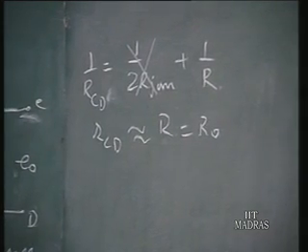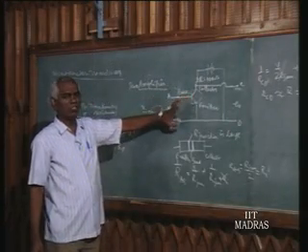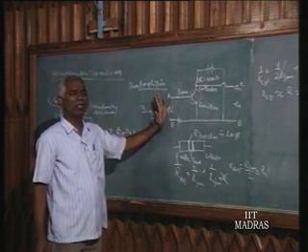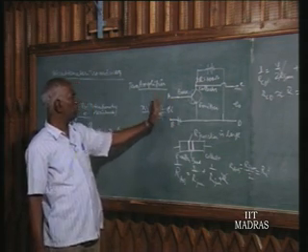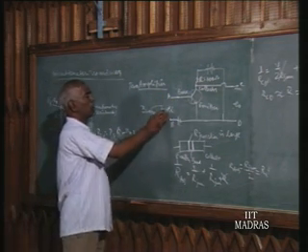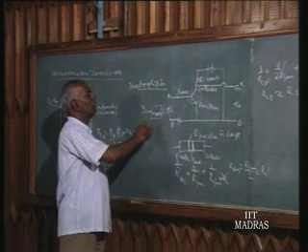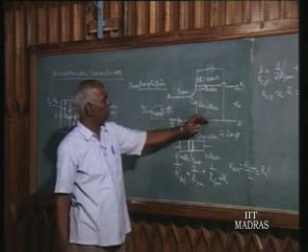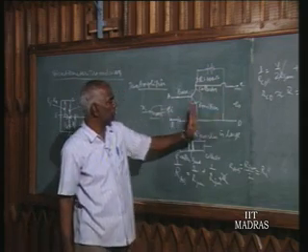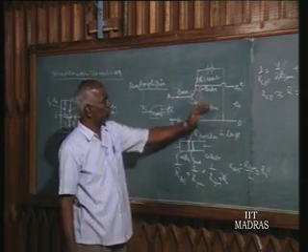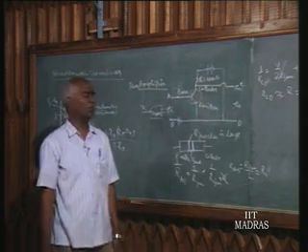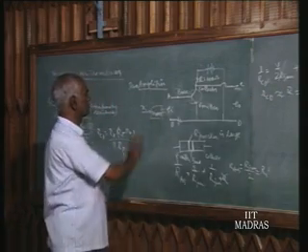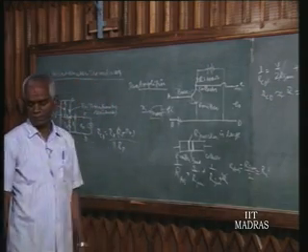That is how we see an amplifier possesses simultaneously a higher input resistance, so that it can be connected to a transducer. It may have 10 times the resistance of the transducer to connect it, and it has a lower output resistance, so that 10 times the smaller resistance can be the input resistance for the recorder. So it possesses both the characteristics.